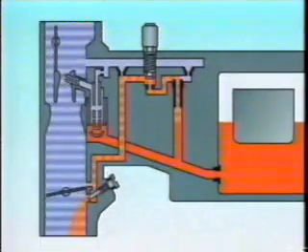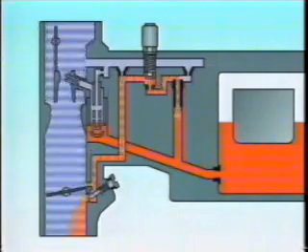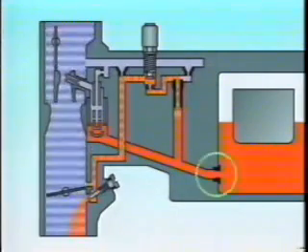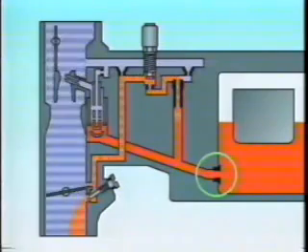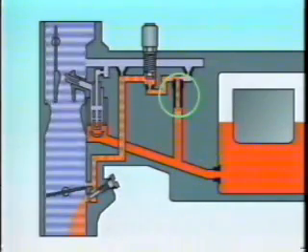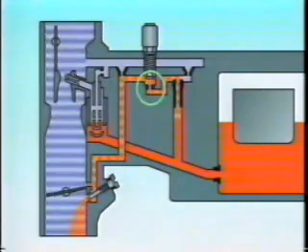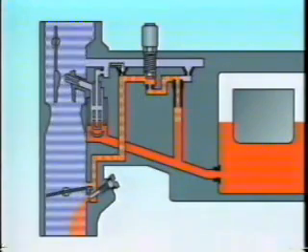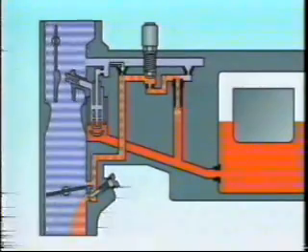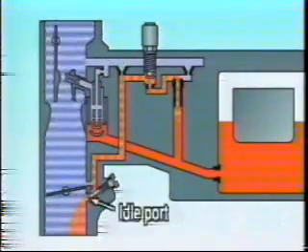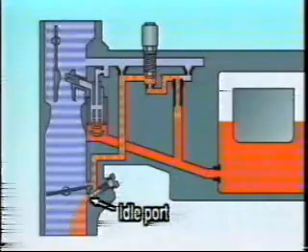The actual flow of the fuel is as follows. It leaves the float chamber and passes through the main jet, then through the slow jet, which controls its volume. It then goes to the primary air bleeder, where it is mixed with air, and then to the economizer jet, where the volume is further controlled. Then the fuel from the primary air bleeder is mixed well with the air and delivered from the idle port.